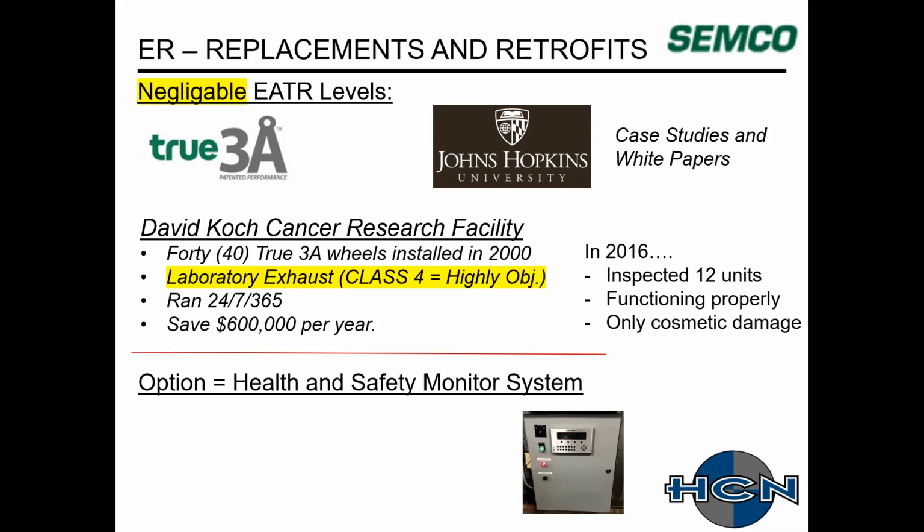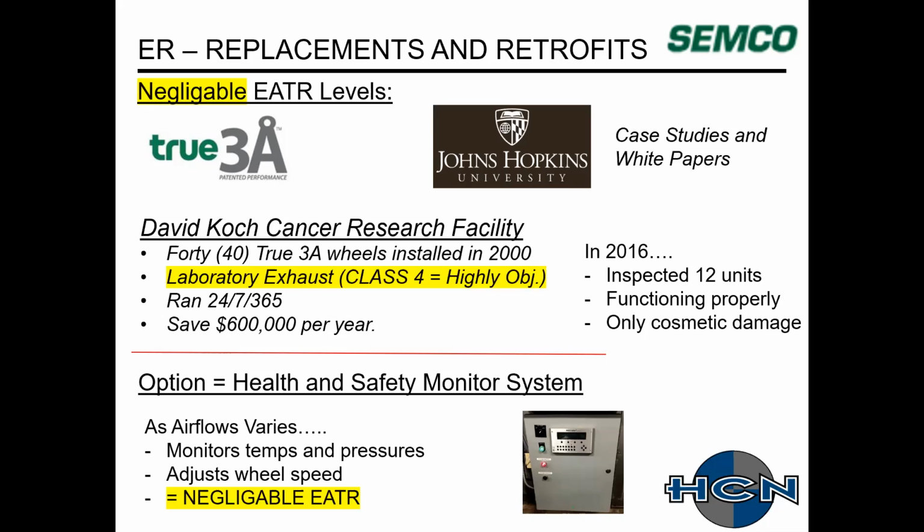And then additionally, for the True 3A, if you want to further ensure negligible exhaust air transfer ratios, Semco has a health and safety monitor system. There it is, very nondescript there. But basically what it does is as the airflow varies from your design conditions, it monitors the temperature and pressures. It adjusts the wheel speed to satisfy your temperature requirements, but it also satisfies your recirculation or just your negligible exhaust air transfer ratio.